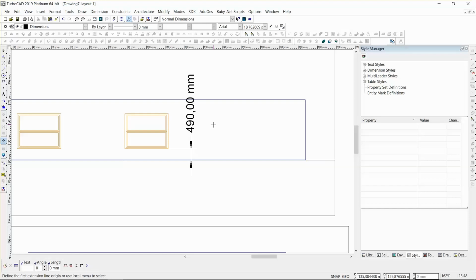Yes. Okay. Alright, yes. So in terms of materials, I know usually we do the house and example, but what are there limitations in terms of an engine for the materials? So TurboCAD does come with what's called a Lightworks rendering. That's the same rendering engine most big rendering programs use. It's got a big library, right? But apart from that, you can take a digital picture of anything and then pull that image into your TurboCAD and create your own material from that image. And save it as part of your materials library.